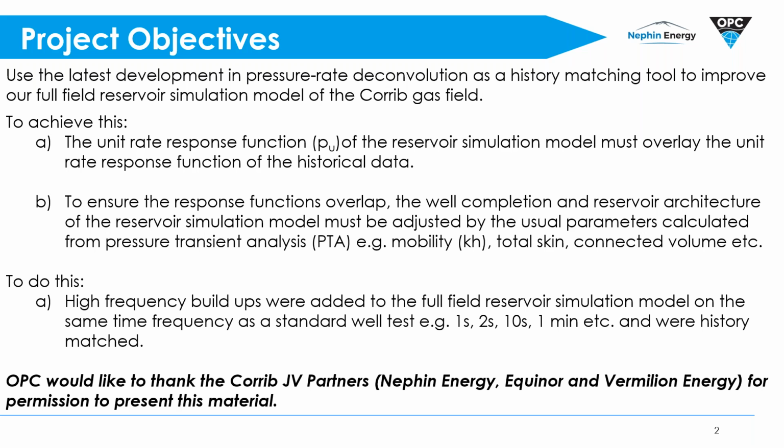So to do this, I added 4 high frequency build-ups to the full field reservoir simulation model, and I did it at the same time frequency as a standard well test, e.g. 1 second, 2 second, 10 second, 1 minute, etc. This is a bit ridiculous, but I wanted to push tNav to see how well it could replicate a proper well test.